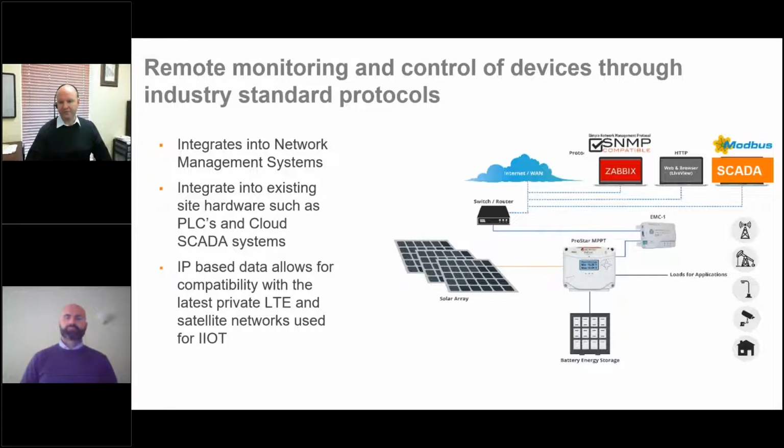Batteries are designed for several days of autonomy, but there are times when the weather's not so great, especially depending on the regions, like the North Sea, as Marco had said, where you need a lot more solar. So all this can be monitored remotely. And generally the products can provide serial to PLC or even IP-based Modbus data over Ethernet. And then from there, it can be measured and monitored by cloud SCADA systems.